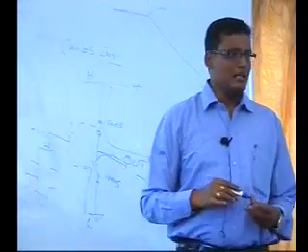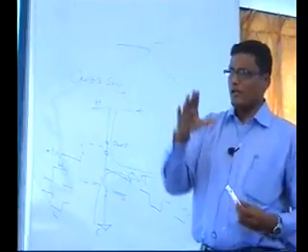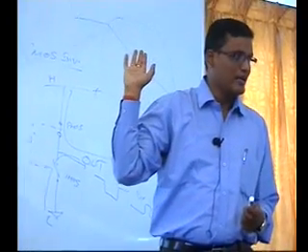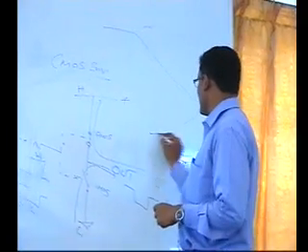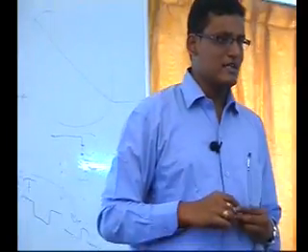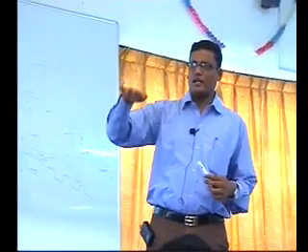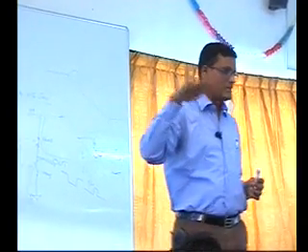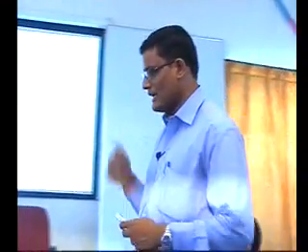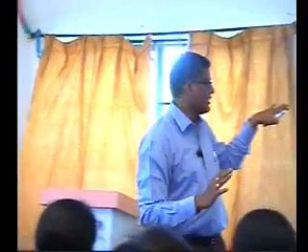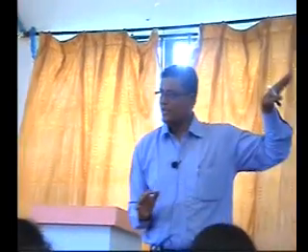The delay in the transition from on to off is very, very high in NMOS logic, whereas this gap is almost ideal or less in the case of CMOS logic. That means the on to off transition is very, very fast in CMOS logic when compared with the other logics. Got it? And there are other factors also which at your level you can understand with this knowledge, right? So what is the answer?